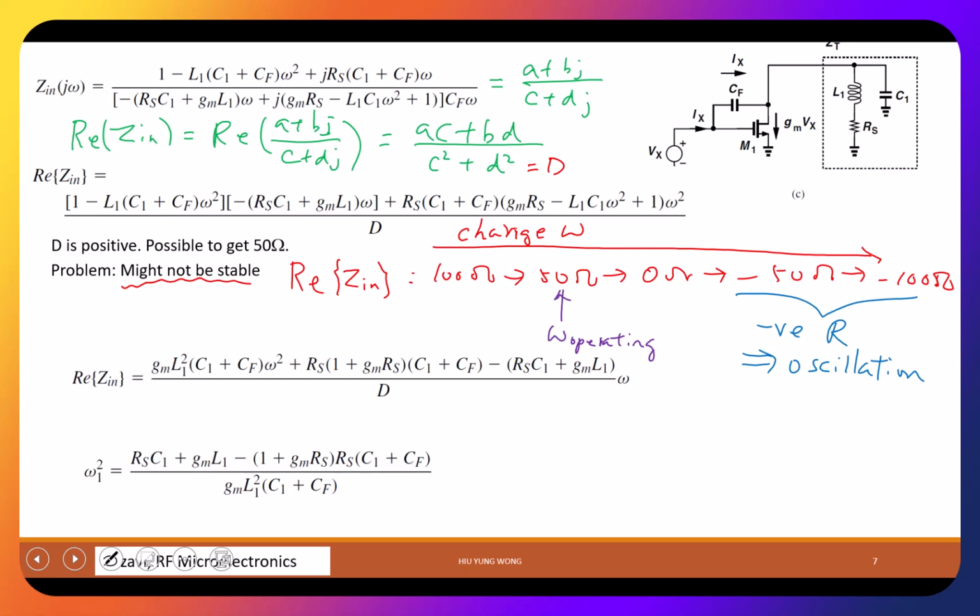Probably you don't remember what you learned in E124. The oscillation is due to positive feedback. You have infinite gain in some sense. So you have noise. Your noise power spectral density has frequency coming from 0 hertz to very high. You did not supply 2 gigahertz, but your resistor is having the noise, right?